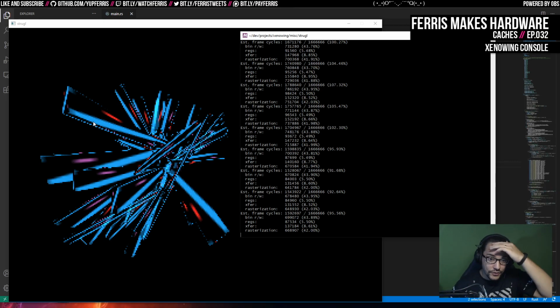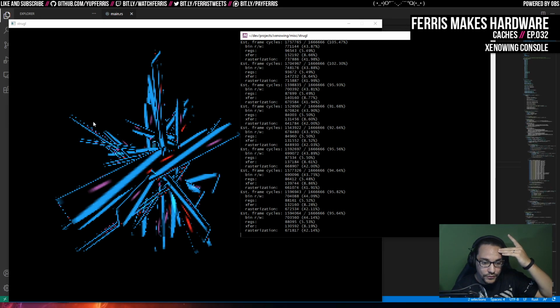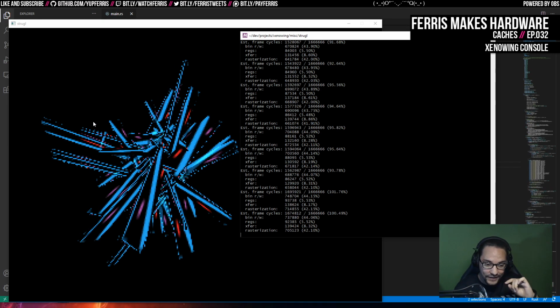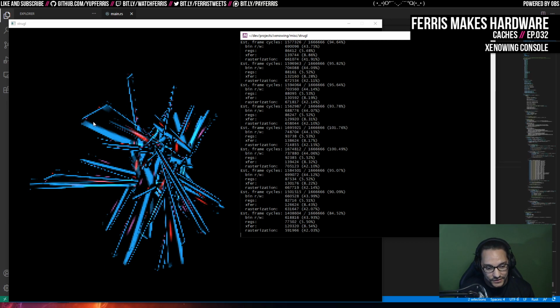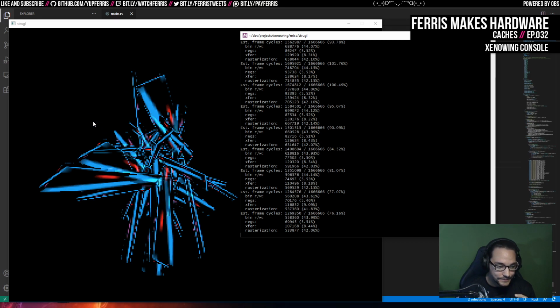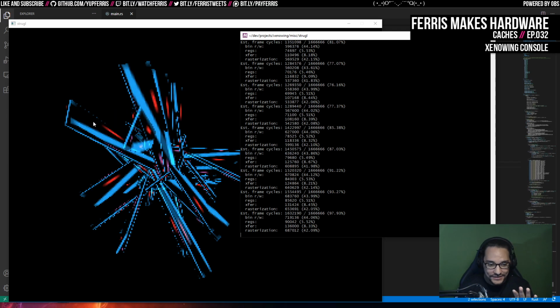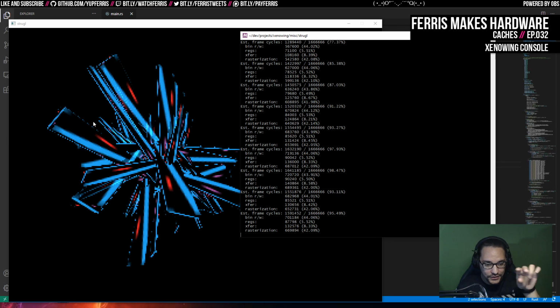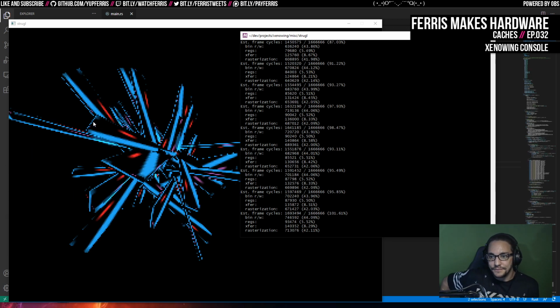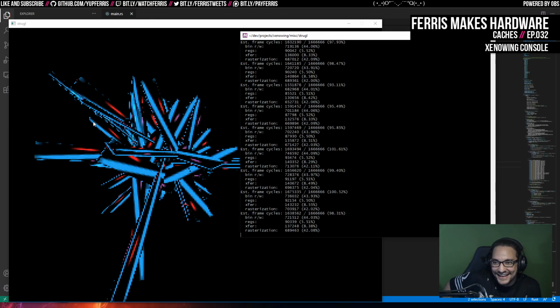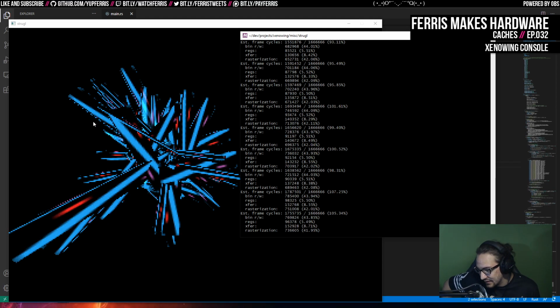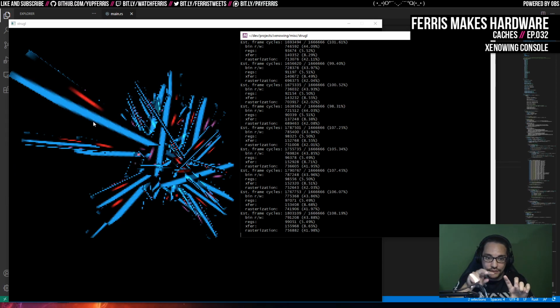Yeah, Daniel Collin, totally. You mentioned you can swizzle textures as well to improve cache cycle. That's actually what I'm doing now. And that's why I said I can read one filtered texel per cycle, because the memory now is actually in 4 different banks in little 2x2 pixel blocks. So I'm already doing that. But that's actually to read 4 at a time.